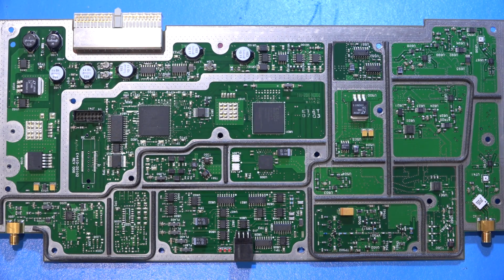And here is the board, and of course, as always, the Keysight engineers don't spare any expense, and things are often really complicated with a lot of resources thrown at some other problems. So here they want to make a very clean synthesizer. So let's see what they've done. We have our 4.8 gigahertz reference coming in, derived from a DRO, so it's very clean. It's got some amplification stage in it, and then it goes into a mystery chip, which is on the other side of the board. So which means that this is where the input prescaler is handled.